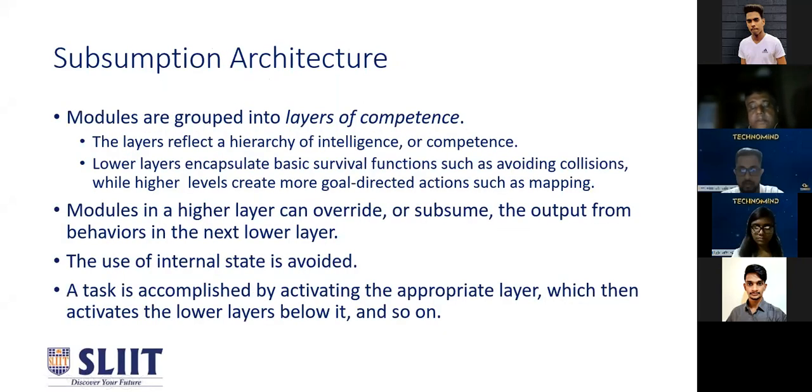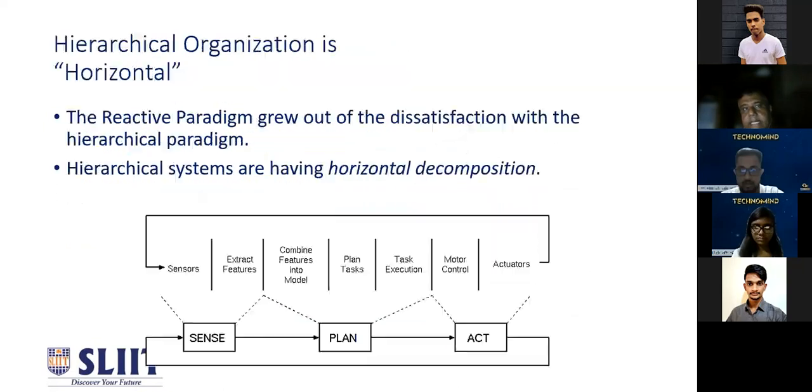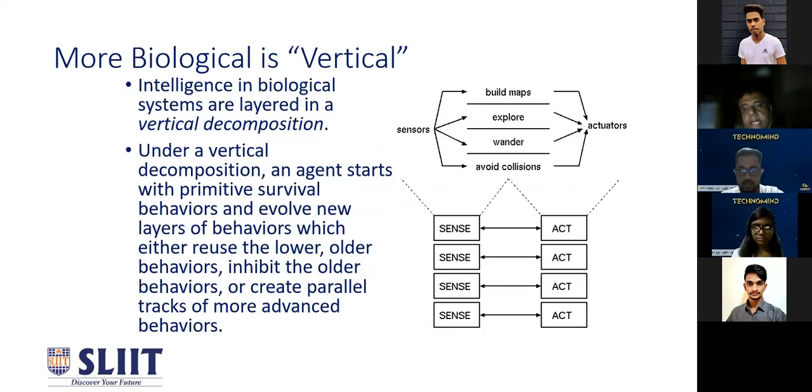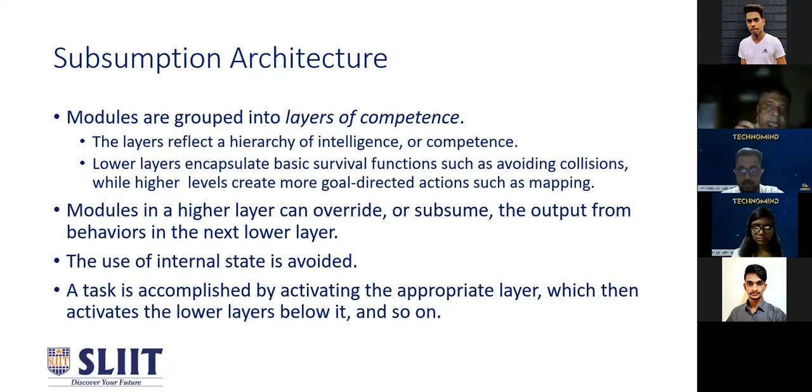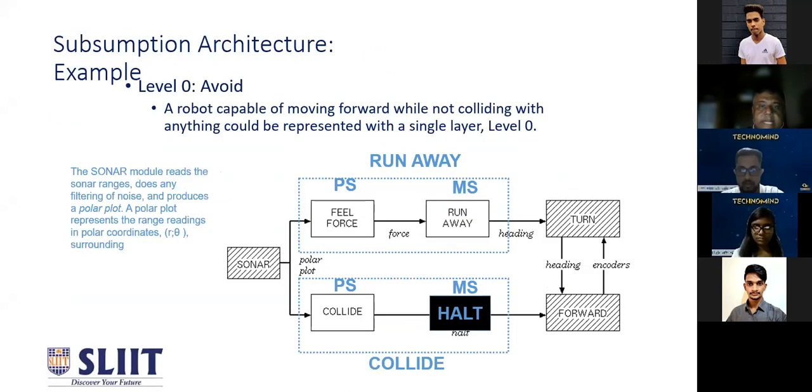And I will explain now. Although I explain, you might be wondering how to do this. I will explain one architecture called Subsumption Architecture, which can be used to implement a behavior-based robotic system. Now, the Subsumption Architecture is actually a behavior-based model. Only thing is, the first two that I explained are two paradigms or two approaches, and this is a particular architecture. Subsumption architecture is a particular architecture that you can use directly to implement this. Now let's look at that briefly.